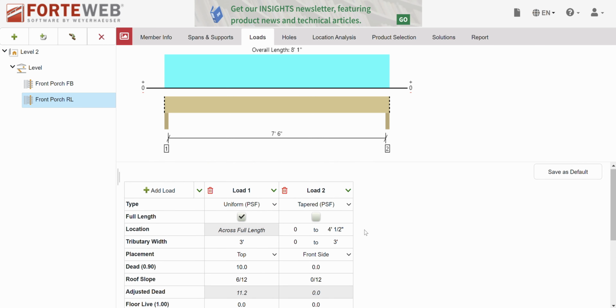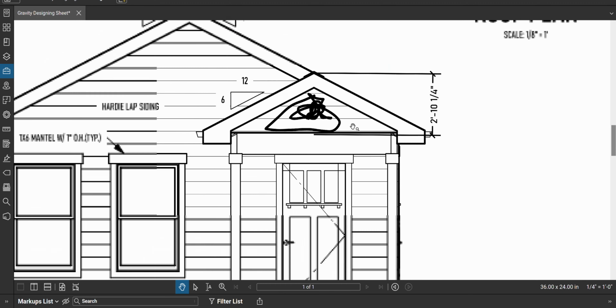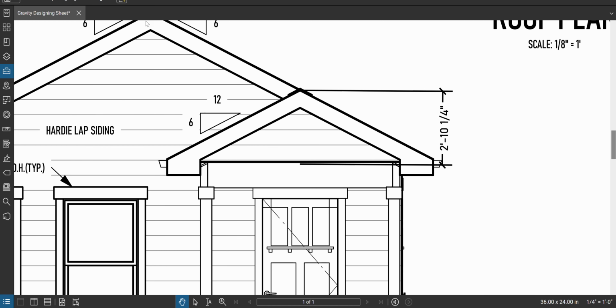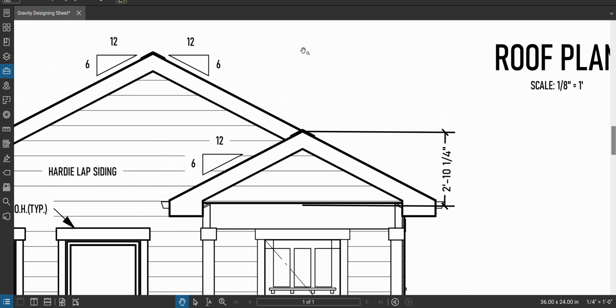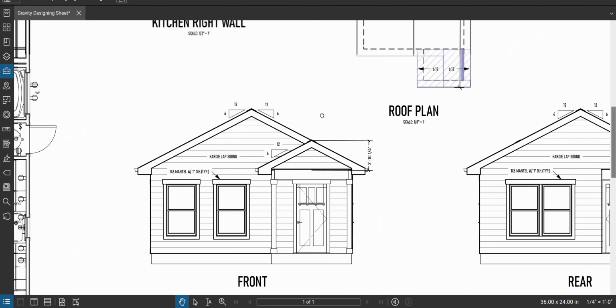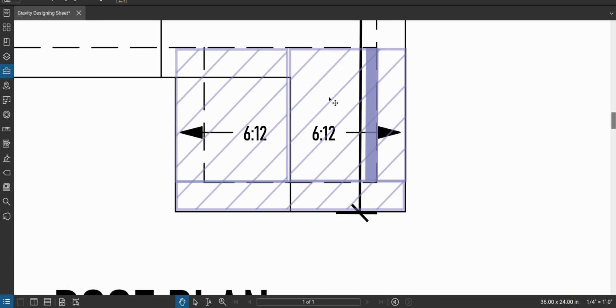All right. So I'm going to go back to the drawing, and so you can follow what I'm doing here. This is 3 feet at the peak. What I'm trying to tell the computer is, it's sort of weird to think about here because the wall is a vertical thing, and the taller the wall, the more weight. But I'm describing it in a horizontal way, right? So when I do the roof and I'm talking about tributary area, I'm always looking down. I'm like, well, how much weight am I looking at in terms of the area this is holding? Well, the wall is right here, right? I wouldn't look down to know if it was more weight.